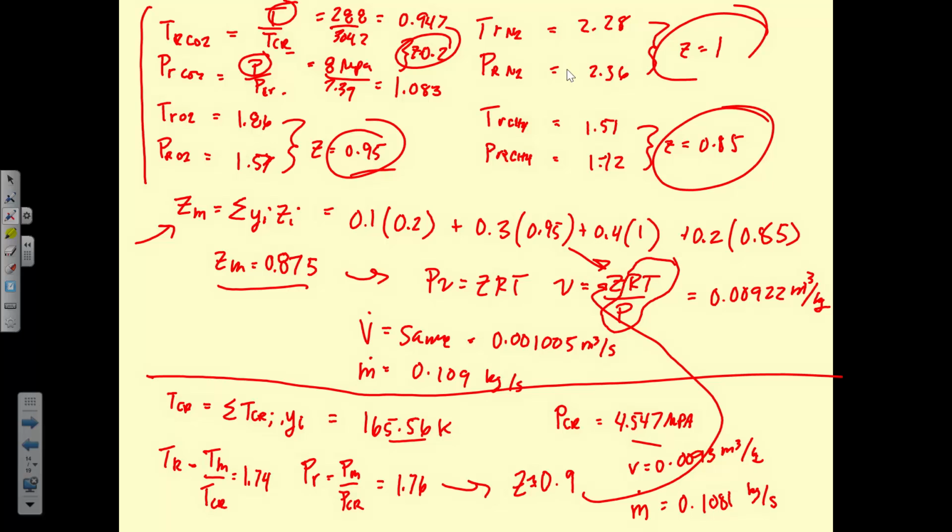Okay, so these are all iterations of the same basic concept. One is that you're just assuming it's an ideal gas. The second is that you're assuming it's not an ideal gas and you're finding a correction factor for each point in the graph, and then finding this average Z value. And then the third way is that you're finding an alternate or a pseudo-critical point and using that to calculate your Z value. And so you get different answers. This 0.95 is different from this 0.9.